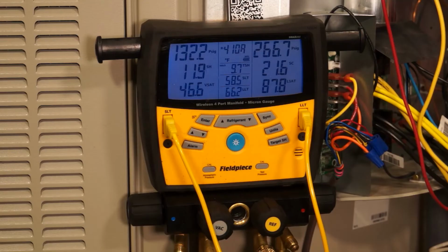So when you're out in the field doing this test, just take the top off, leave it off, stick your probes in there on your common suction line, and then whatever line coming off the bottom on that reversing valve, whether you're going to be testing it in cooling mode or in heat pump mode, and take your temperature readings. Again, 7 degrees is about your max that you want to be at. If you're over that, we want to make sure that the test that we're performing is as accurate as it can possibly be, that we're using thermocouples and not lasers to test the line temperatures, because you don't want to go through that whole process of changing a reversing valve and it not be a reversing valve.